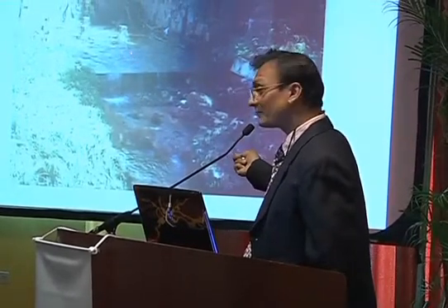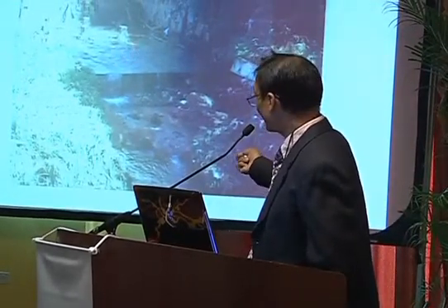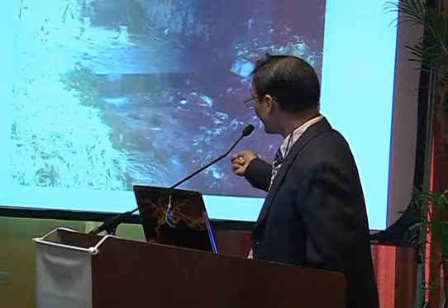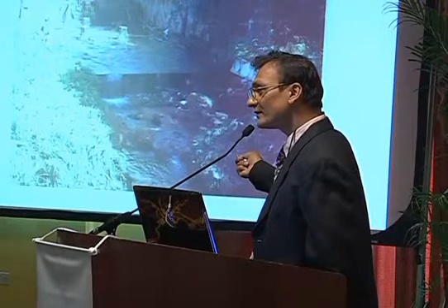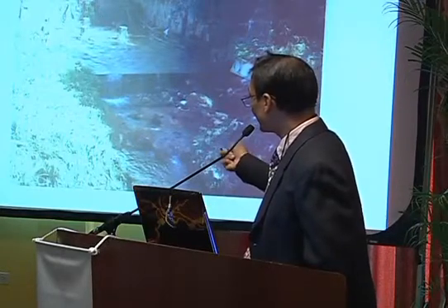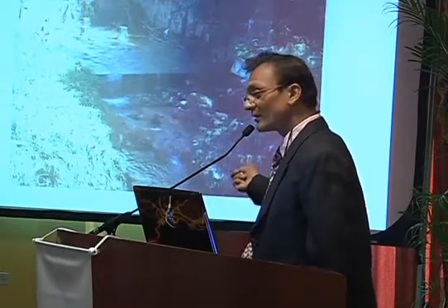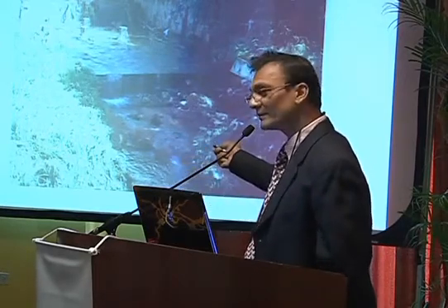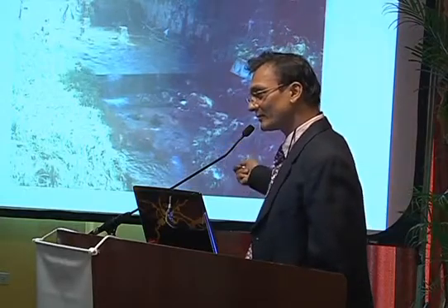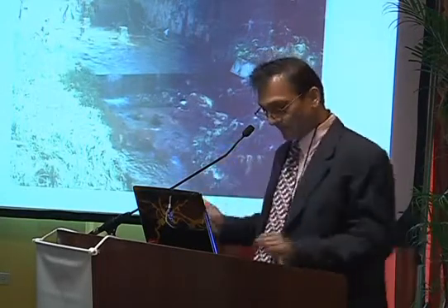Issue with proper management of the paved area. This should have been not sloping but horizontal. That increased the energy of the flood, or the water coming over this weir, and it caused about a 0.5 meter scouring. So while you're trying to hold the sediment back here, you are providing the sediment there.